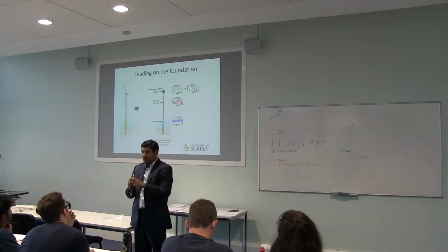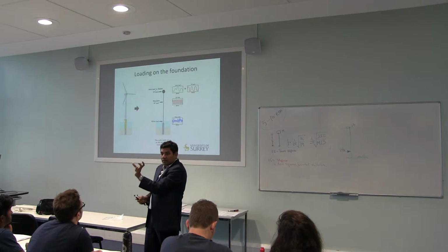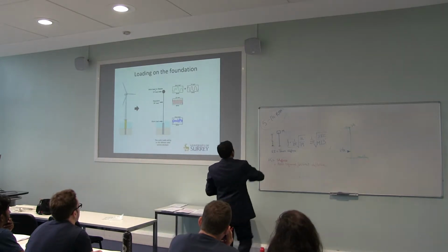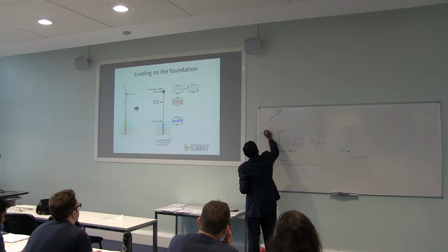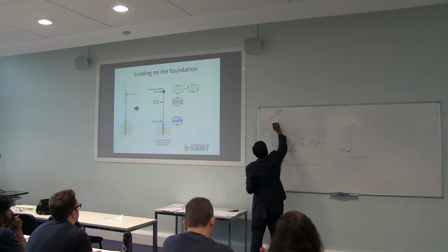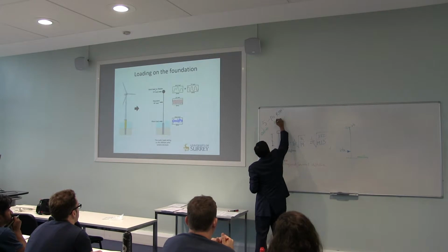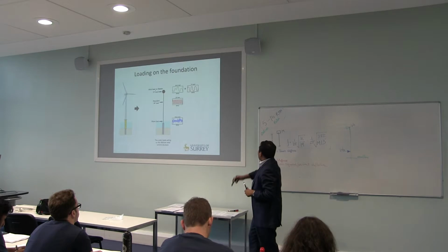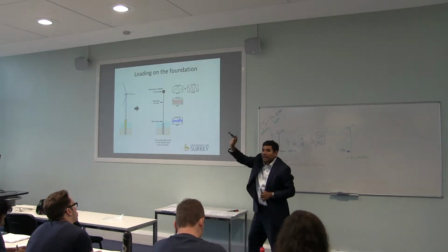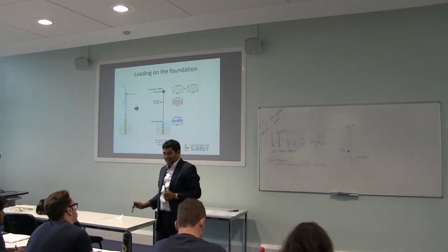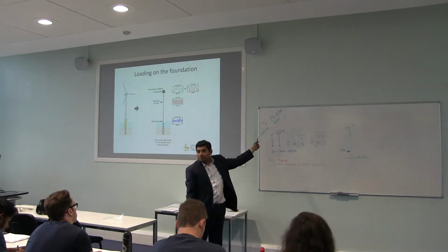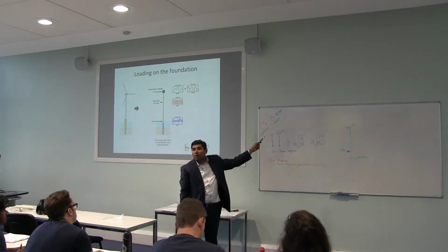So that's the range. If you see any turbine, they will tell you the range at which it can operate. This is called the cut-in speed, and that is called the rated RPM. Rated means if you turn at 14 RPM, you get the maximum power it is rated for. Cut-in is the minimum speed. You will not see it operating lower than 5.